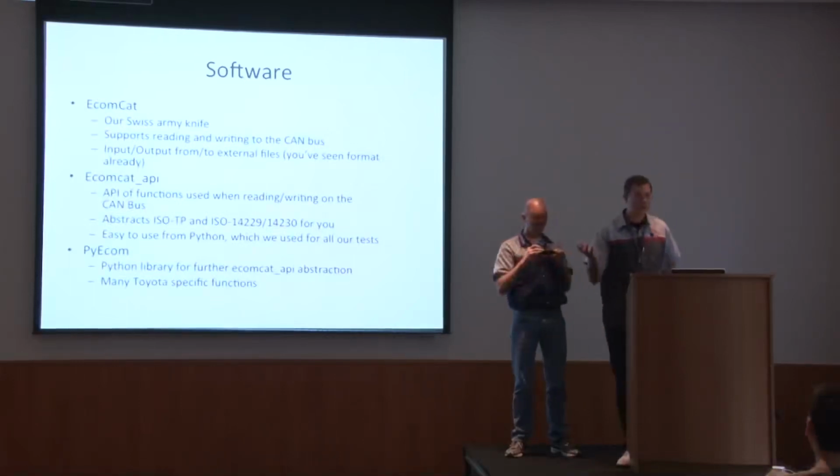We would sit there and read messages on the wire, and we built in some functionality to send multiple messages, continuously loop messages, filter on certain IDs. It's not very well written, I would say, but it definitely serves the purpose and is very useful. This is a tool when we wanted to figure out how parallel parking worked. Charlie and I would be out parallel parking our cars for hours on end for a couple weeks, looking at our computer and using this software to narrow down the IDs that were used for the parking.